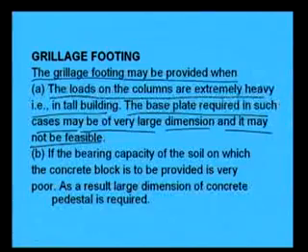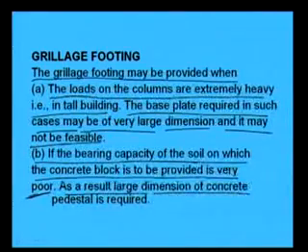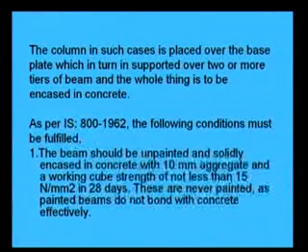Another thing is, if the bearing capacity of the soil on which the concrete block is to be provided is very poor, then a large concrete pedestal is also required. So, in that case also we go for grillage foundation.